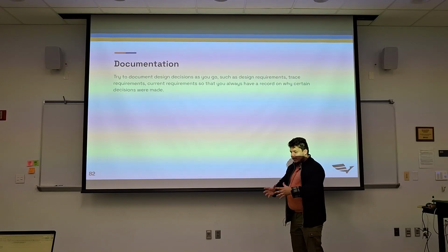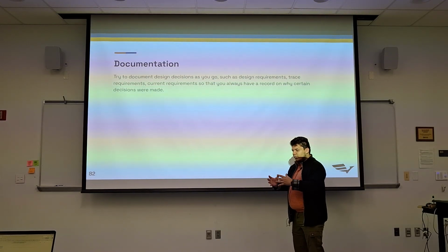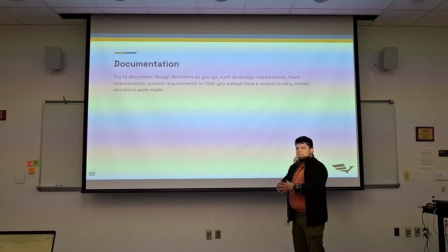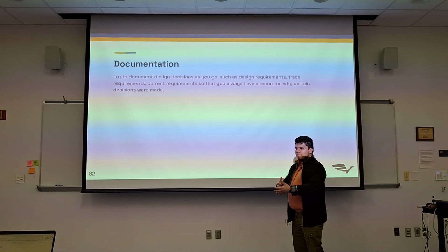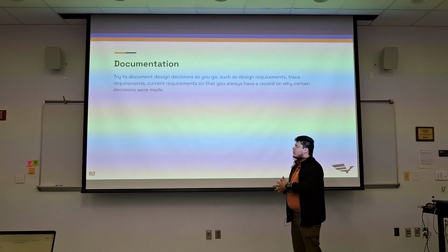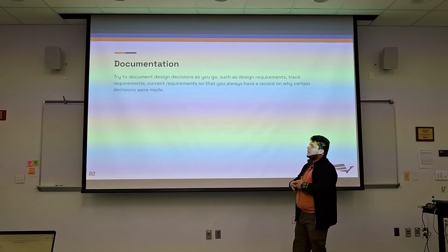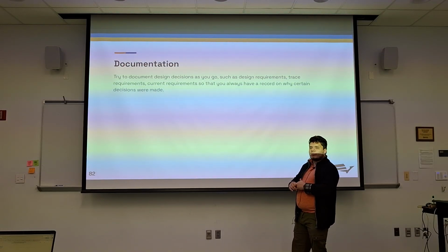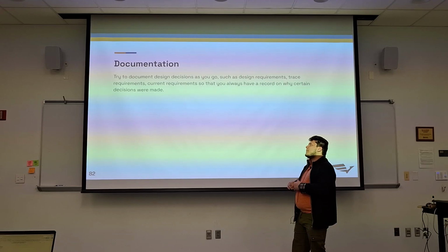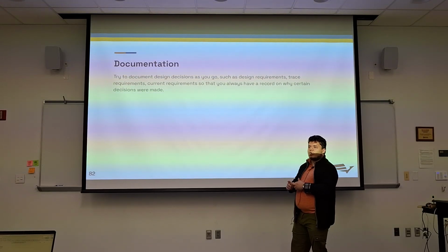And so having that on record gives you something concrete to reference when you choose the trace widths. How much copper do I need for 3.3 volts? Am I going to surpass an amp? Probably not, so I'm probably fine. But always keep a record of that, whichever software, whichever way you do. Keep a record on why you chose 4 layers, what those 4 layers are, or what the 2 layers are. That way it's easier to go back later on in the design.